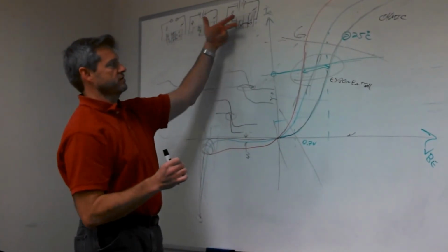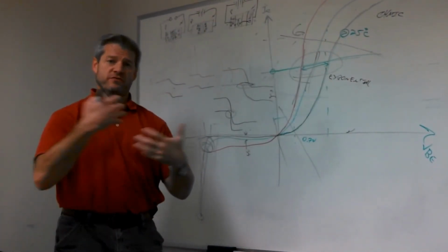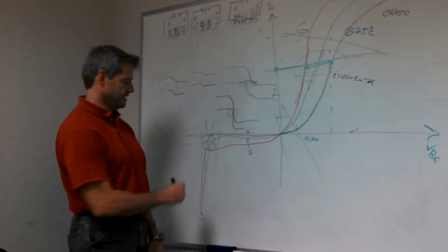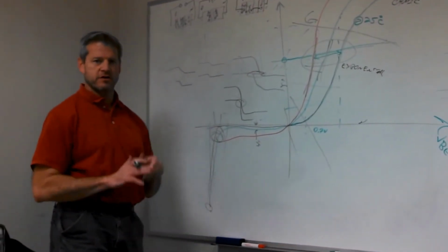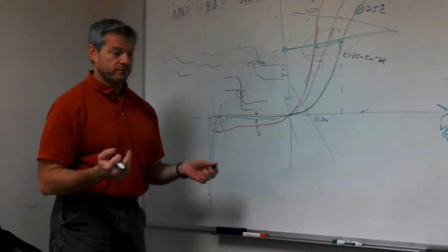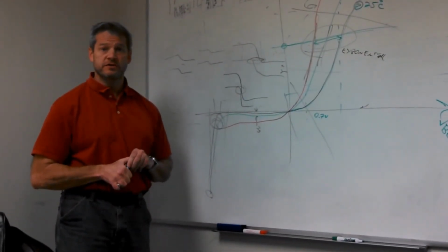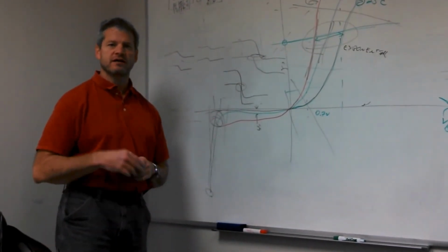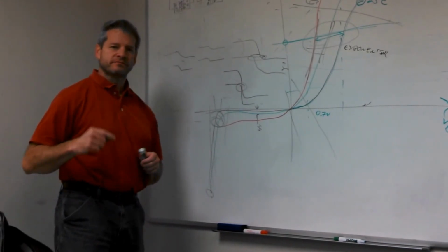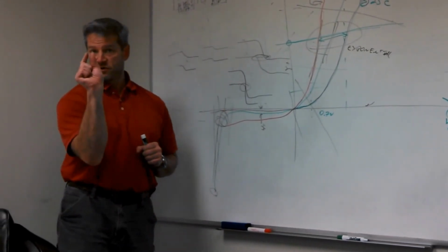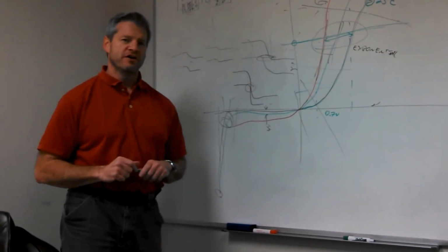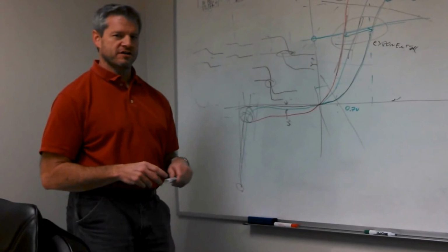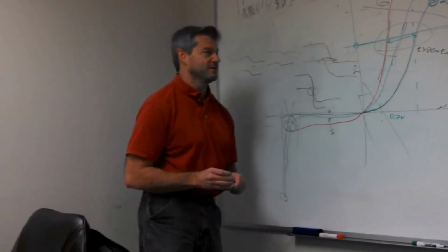Well, and of course, the same thing's going on the other side. Holes are going the other way, so it reaches an equilibrium, but now you're really pumping a lot of current through this thing, and now you're way down here somewhere. And currents can get really high, and avalanche photodiodes are made to do just that. One photon comes in, and you get a million electrons out, or a large number of electrons out. It's a way of amplifying your signal. And as long as that's just for a little pulse, no harm done. The heat goes away, and we're good. But if that keeps going for a long time, bad things happen.